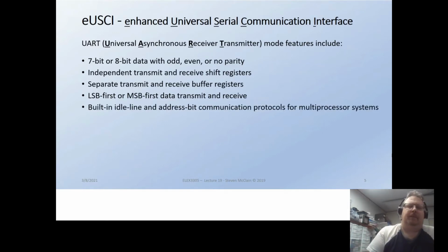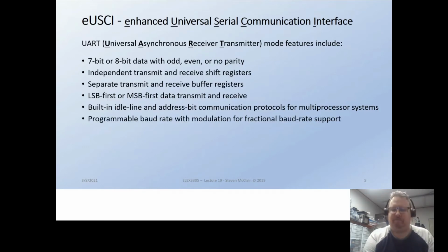And it does have some hardware mechanisms for detecting idle lines and detecting break and detecting a couple of other strange situations on the line, and also mechanisms for doing addressing in multiprocessor systems. So if you want to do one UART connected up to a whole bunch of processors, you can have ways of addressing them and doing tricky protocols. And there's hardware to help you.